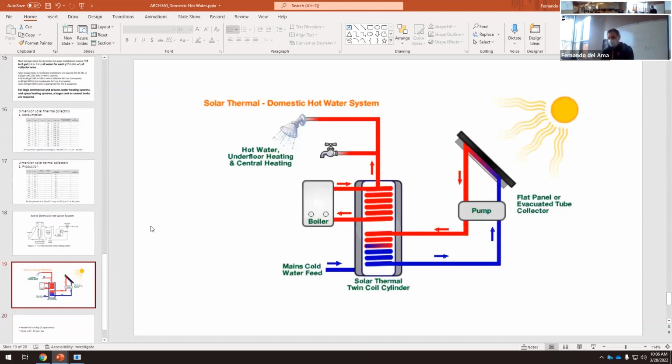We're going to do something like that, the most simple installation that we can have. Okay, so we have solar collectors, we have a tank, and then we have domestic hot water. We need a boiler, and this is the auxiliary system. If we don't have 140 Fahrenheit here, and it can happen because on a cloudy day we won't have enough sun to heat up water up to 150, we need an auxiliary boiler.